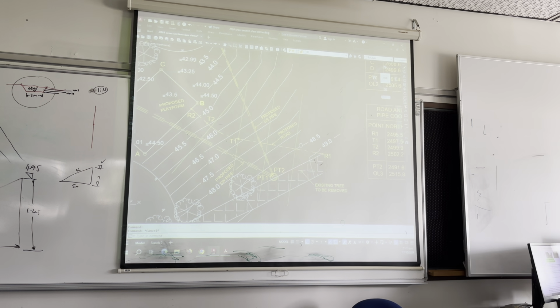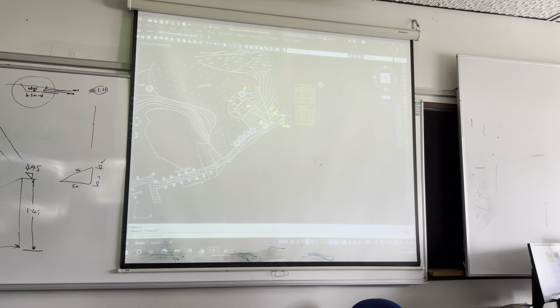I'm going to offset, the road is how wide? 3 metres. I'm going to offset that 1.5. So there's our road. And I said to you I'd do between there and there. Okay, so I'm going to draw that first cross section up.